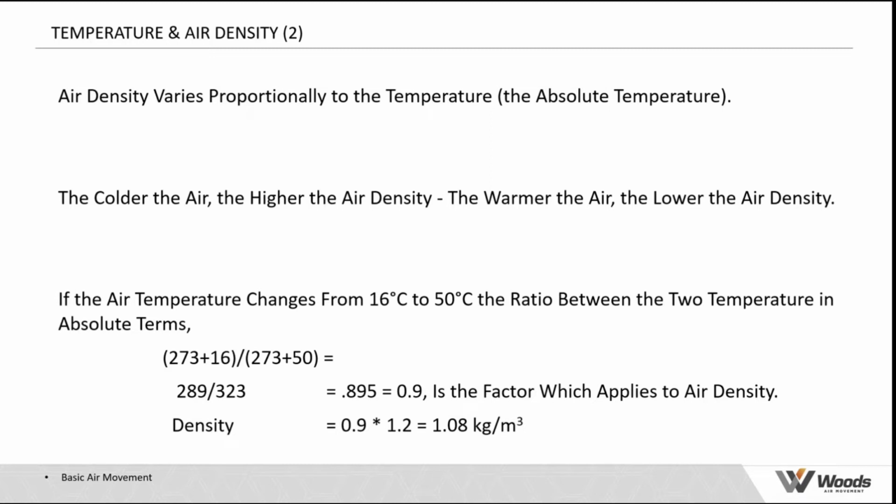The importance of that, if you're doing fan selection, is to know at what density your duties have been calculated. Because if your duties have been calculated at a low density, we need to make sure we select the fans at that. And you can always model that within the software. So all of the things I'm telling you here all happen within the software.